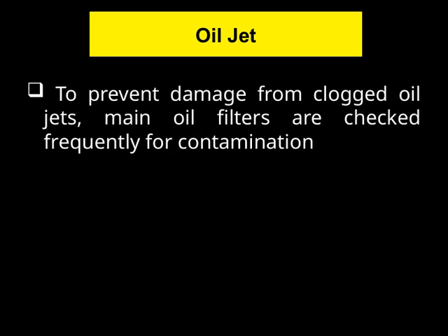To prevent damage from clogged oil jets, it's really important to check the main oil filters frequently for contamination. When these filters get dirty or clogged, it can restrict oil flow, which might lead to engine issues or even damage. The oil jet, as you know, plays a crucial role in delivering oil precisely where it's needed. So, keeping an eye on the filters helps ensure that the oil jet functions properly. Regular inspection and maintenance are key to avoiding costly repairs down the line.